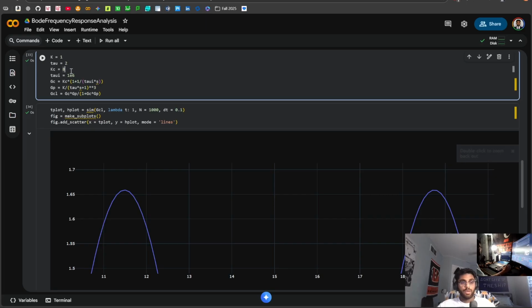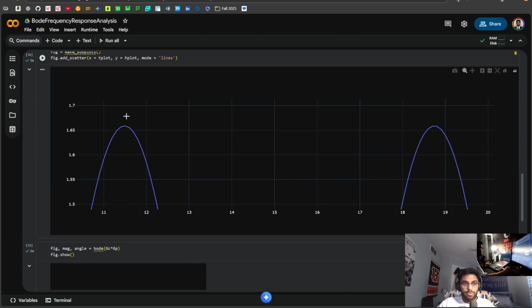First off, we found that ultimate K, so times 0.45. And this is the Ku times the tuning Zn parameter. And then to find that tau I, it's 0.83 times the time period between a full oscillation, so between two peaks.